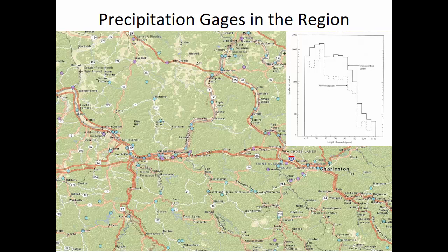Interstate highways, for example, typically have their drainage systems sized to handle the 100-year storm, so that during the 100-year storm there isn't going to be water getting onto the roadway.